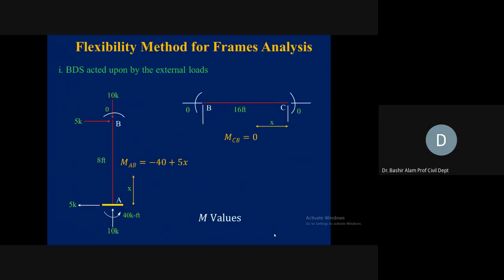generate equations. This is now, we start under the actual load, we start from this BC member. So at C, as there is no load, all the member end actions at C are 0, and all member end actions at B are also equal to 0. Member AB, now this 5 kip cannot be put on this BC member because we have removed the resisting capability here. It can be only resisted at joint A now.